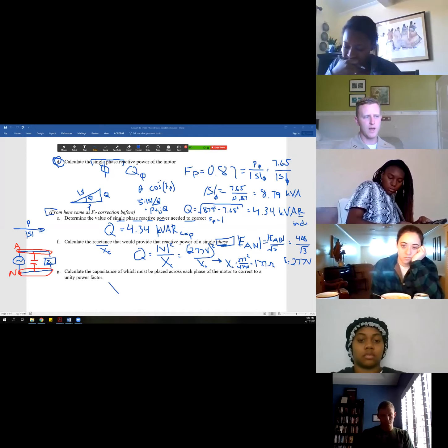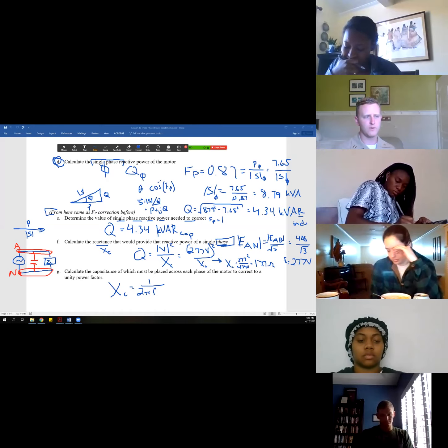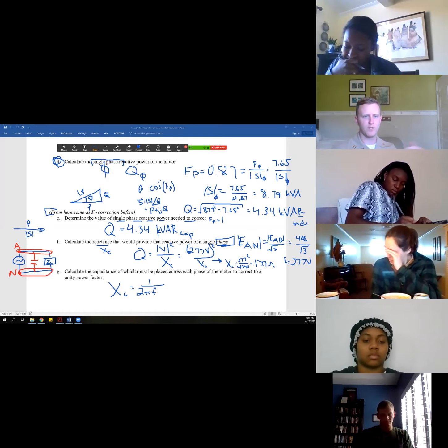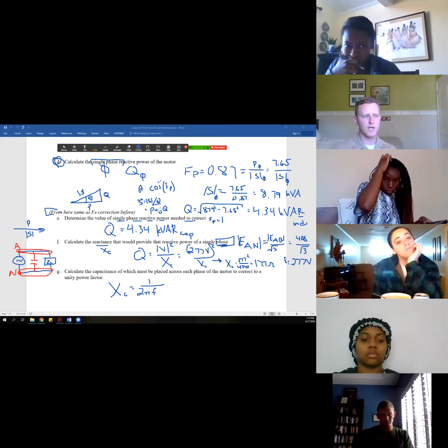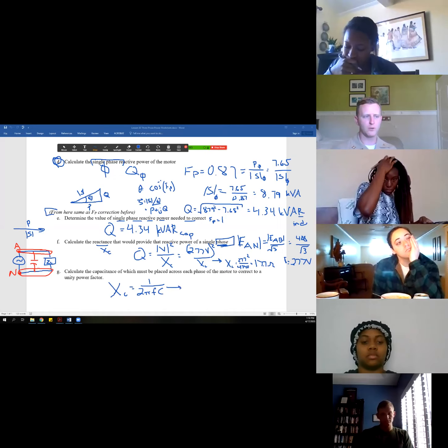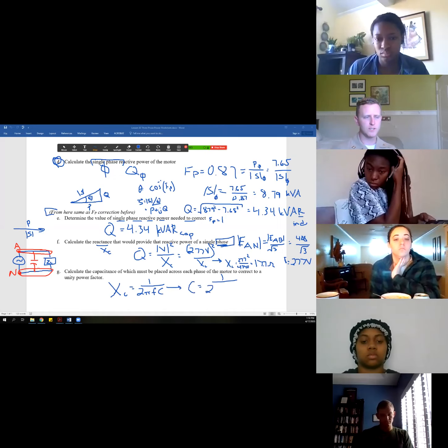And now this is the last step. X sub C, the reactance, is dependent upon a frequency. If we think back to all the different frequencies like resonance and filters, different frequencies create different reactances. But what we need is the one of our particular circuit. On our circuit, the frequency we said was 60 hertz, which is most common in America.